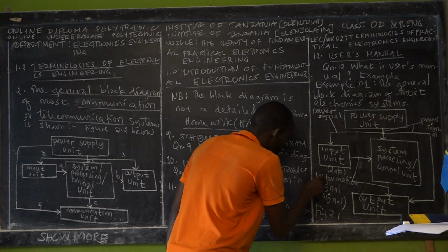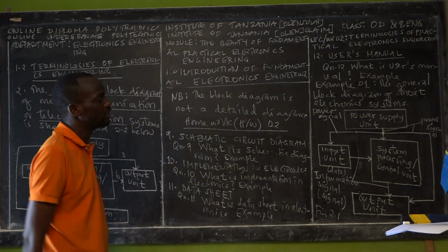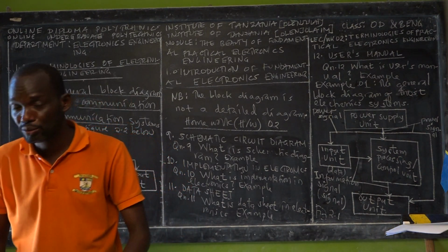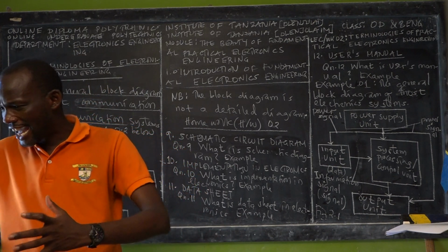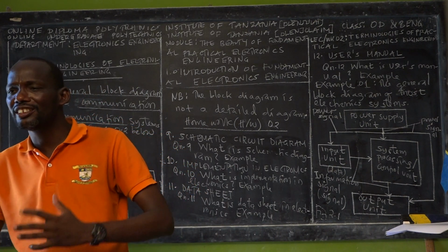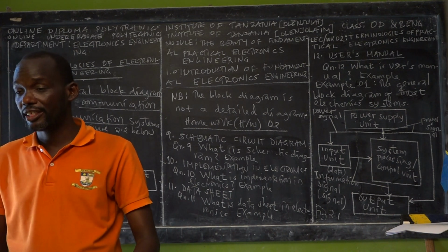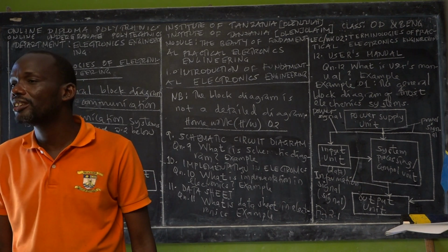Yes. So as a beginner in practical electronics, you have to bear that in your mind. Once you see any block diagram or schematic diagram, you have to think: what are the arrows or lines representing, the information signal or the power signal? It will simplify your thinking, your troubleshooting, and your understanding, more than you think.